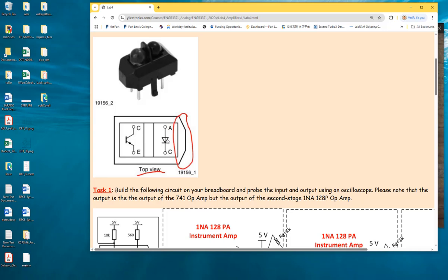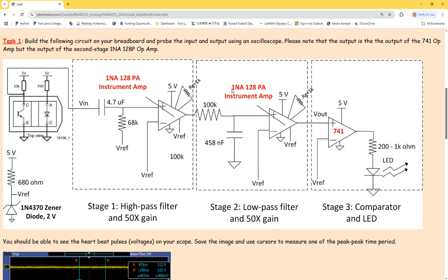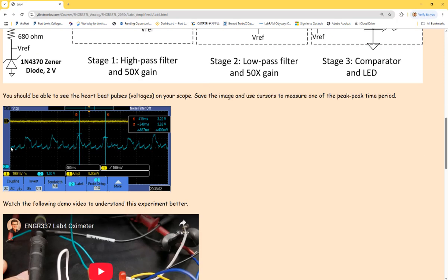So eventually, because you have a different amount of red blood cells at the fingertip during different time frames, you are seeing a different received reflected IR light by the sensor. Okay, and then you can use a peak detection circuit to find out. You can see this, right? So depending on the amount of red blood cells in the fingertip, the receiver is receiving a different intensity of the light, which is converted to the electric signals.